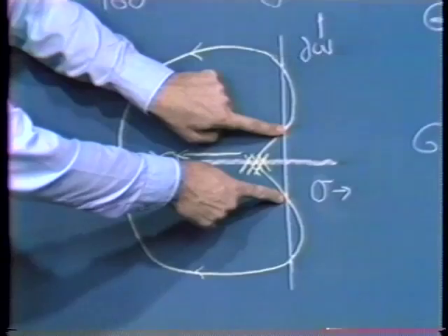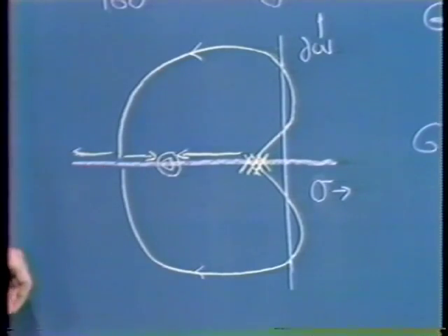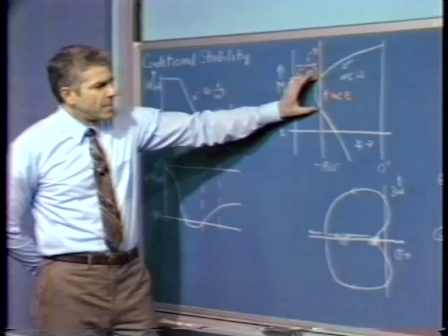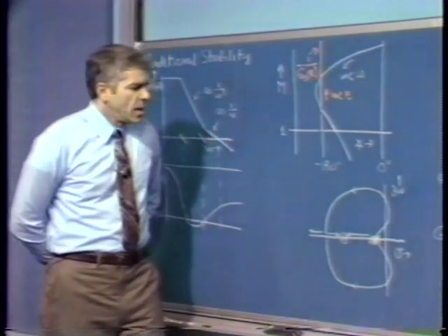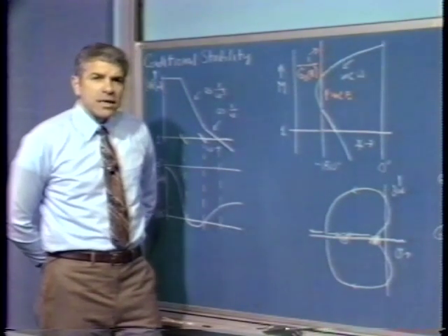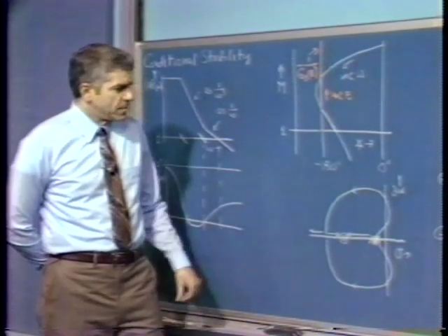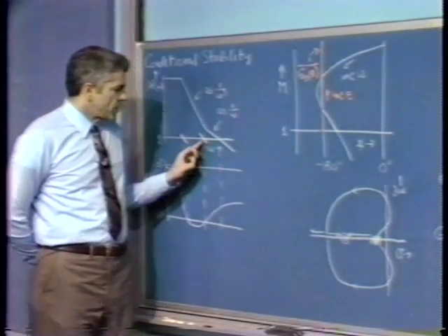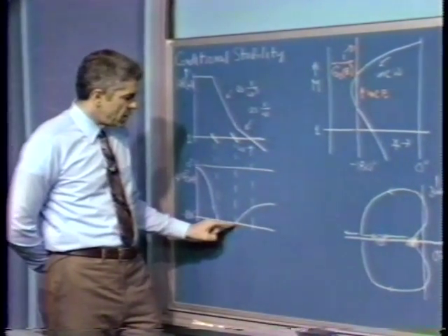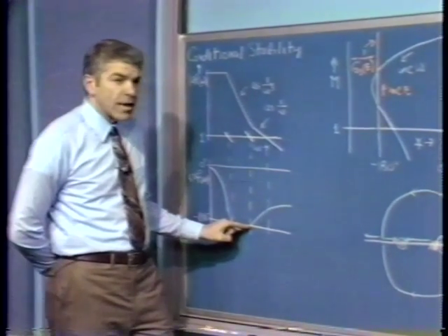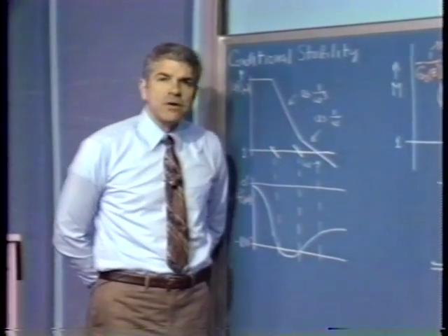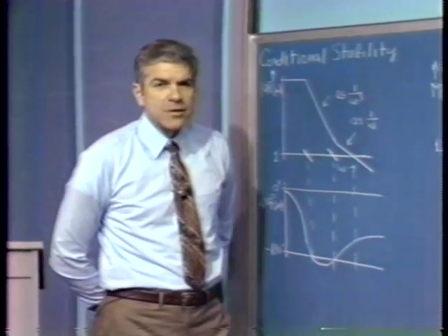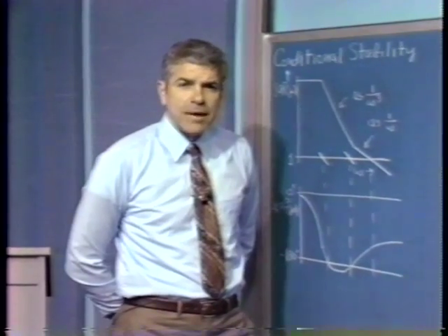We might end up at this point. That's, again, a borderline stability point. Well, we see either from the classical describing function analysis, from this sort of an analysis, or from the root locus analysis, that there are two values of E that result in a system that has unity magnitude for the loop transmission at the frequency where the angle associated with the AF product is minus 180 degrees. And we have to consider which of those represents, if either of those represents, a stable amplitude oscillation.